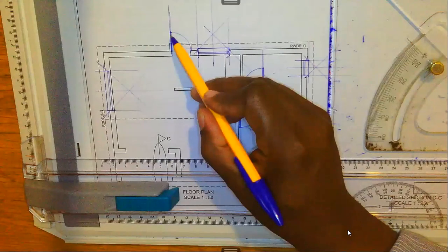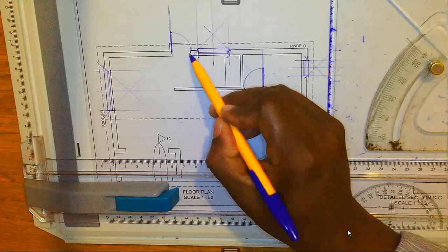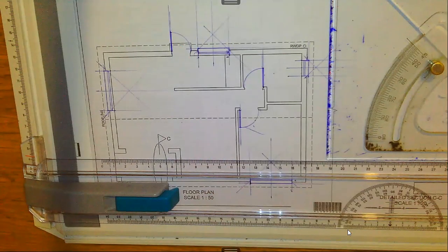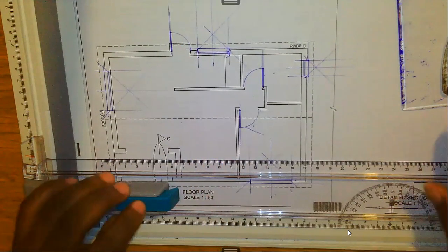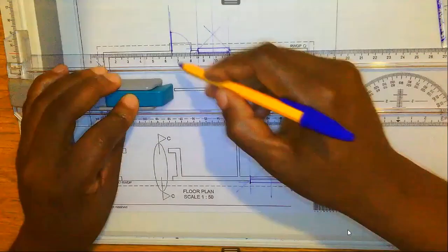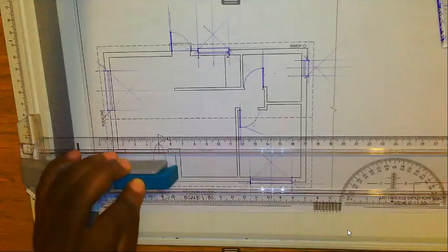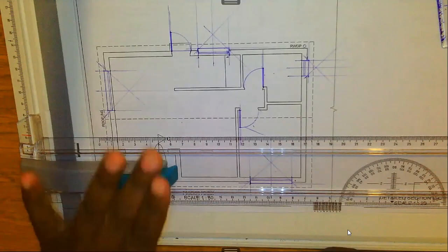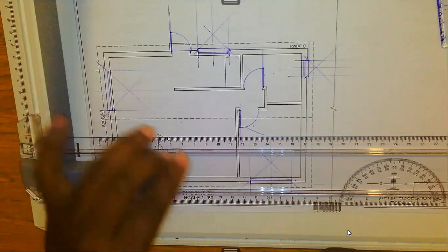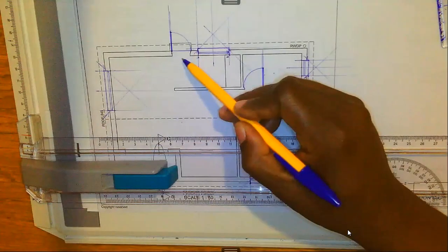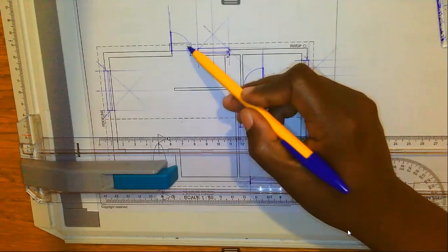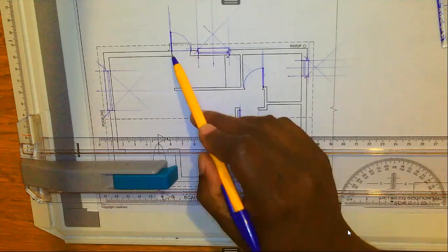That's our door, okay? Right, there's one thing that you should consider in terms of the door which is located on the external wall. Normally, you should provide a line like this. Boys and girls, what do you think that line is for? Right, as you enter the house from the veranda or from the natural ground level, there is a step up. As you exit, there is a step down. So that line is representing the step up or a step down.